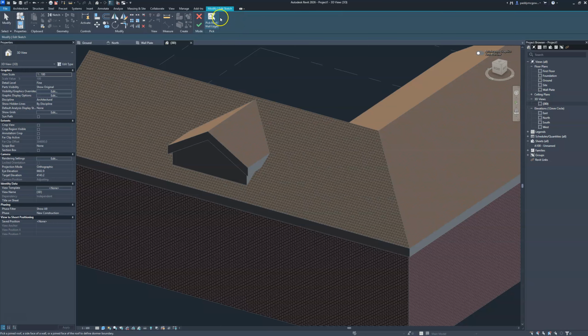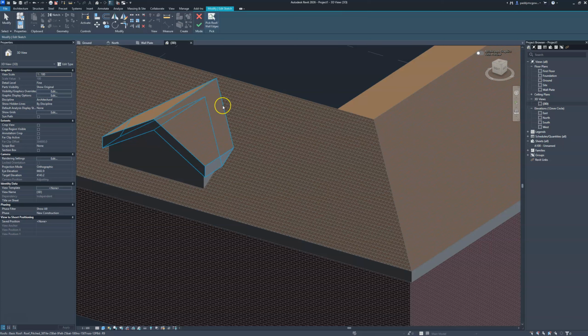You'll notice we don't have a sketch, okay? We can't draw lines, but we can pick entities, okay? So let's pick this roof. So I just click there and you can see the sketch lines come in. I want this wall here. Now, if I hadn't trimmed it, I would probably find it quite hard to pick it. There, I'm hovering over the bottom. If I hadn't trimmed this wall, the bottom is inside there. It'd be a little hard to pick, okay?